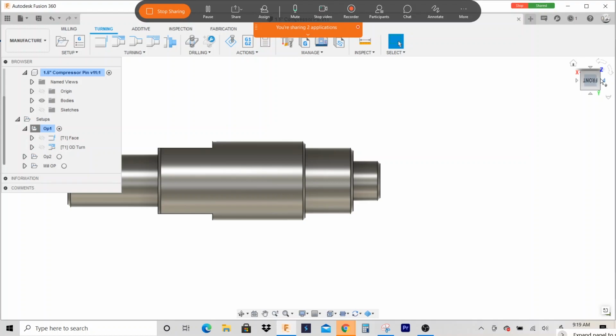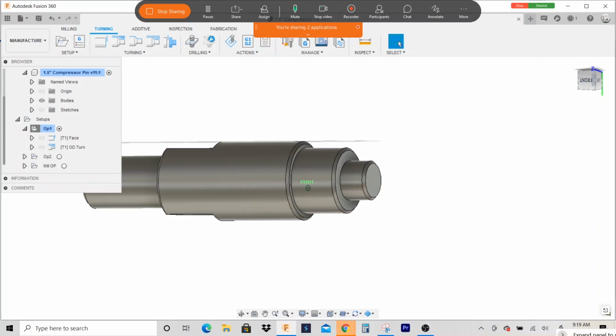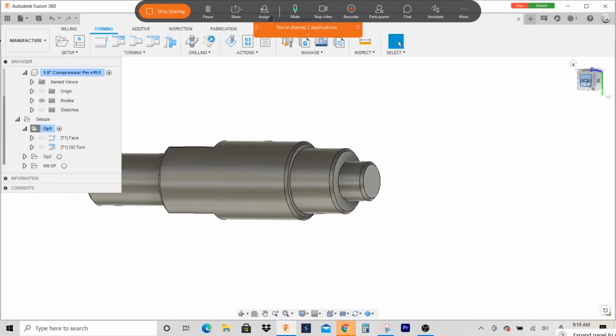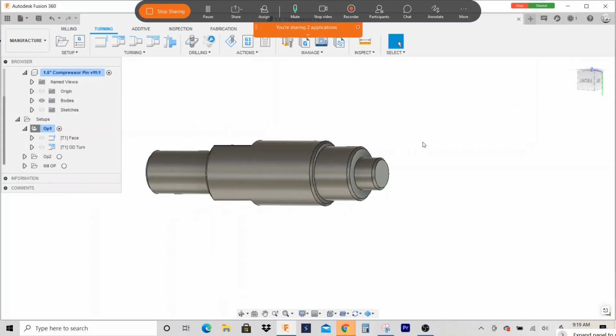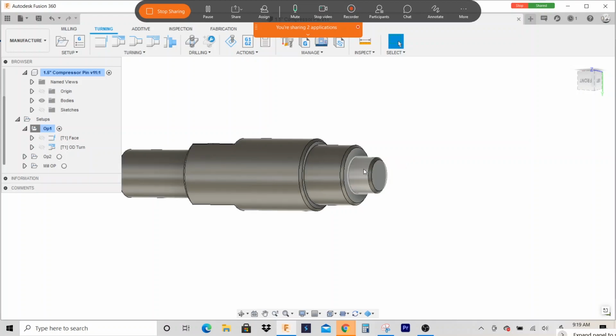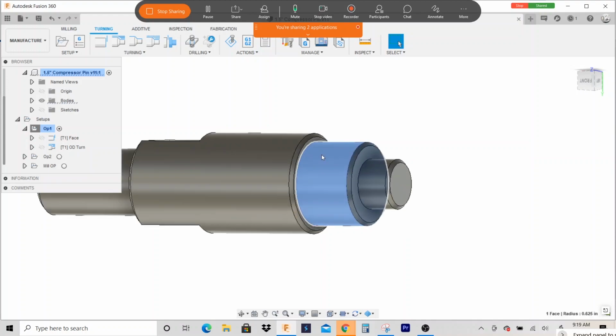So depending on how many parts and the complexity of the toolpaths, sometimes it makes sense to write a program, sometimes it doesn't. Sometimes you could just take an existing program of a similar part and modify a couple of things, like if you're just turning an OD, and the existing part is going back 1 inch and this one's 1.68, you just change the Z depth and the X starting position and ending position.